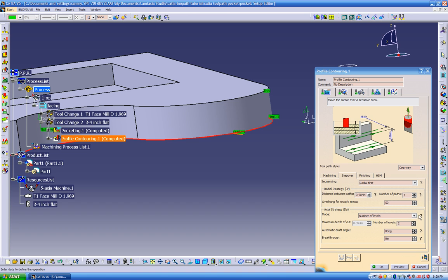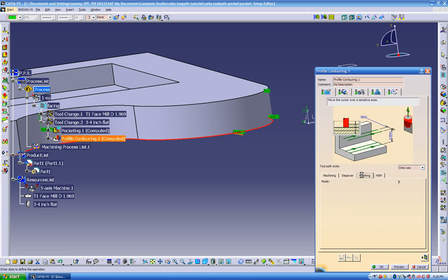So we're gonna make two. We're gonna go 2 times on axial and 1 time on the finish. So we're gonna do one nice finish along this whole wall. So we're gonna put only finish side finish last level. Just 1 time at the bottom. And it's gonna ask us over here, what's your side finish? So that's what we want. We want to make one nice finish at the end. We're gonna make this 20,000. And we don't want to make a bottom thickness. We just leave this 0 for now.